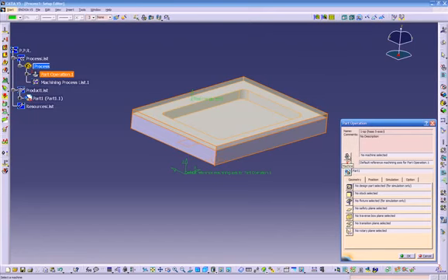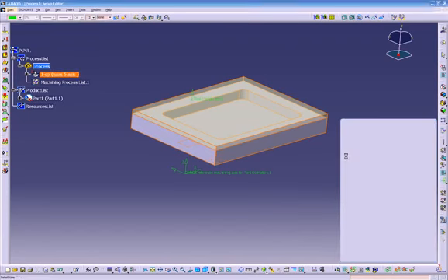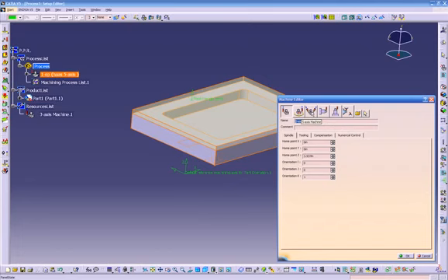Now on the machine, we always have to make sure we go through all this before we click OK. Let's click on the machine and make sure we say it's a 5-axis machine. Because if you don't select 5-axis machine here, once you create a 5-axis toolpath and we create our APT code, the code is not going to be a 5-axis code; it's going to be a 3-axis code, even though the toolpath shows 5-axis. So we have to make sure we specify the right machine before we move forward. So we got the machine.